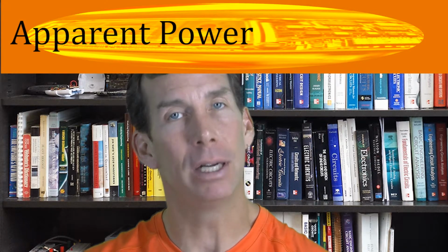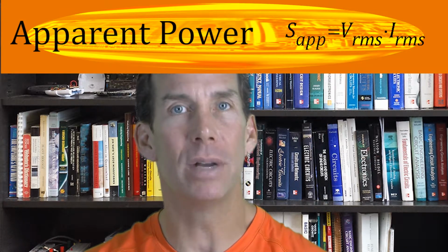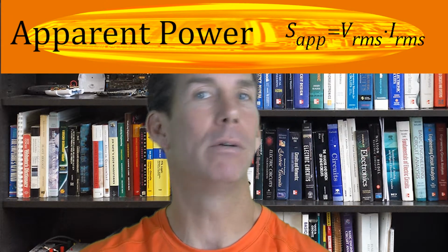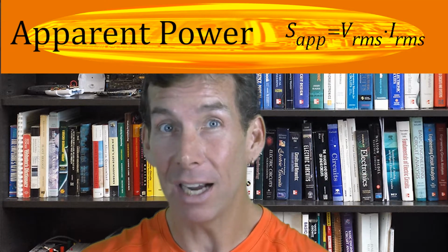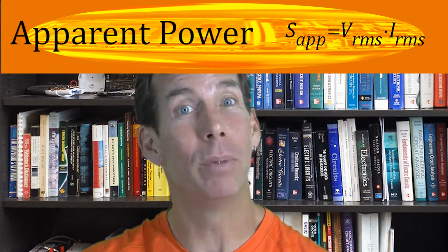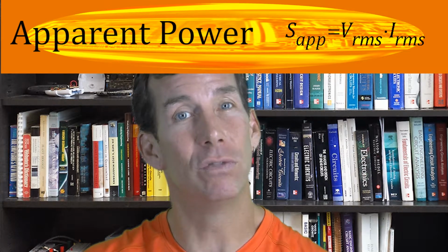Now we need to develop some vocabulary around this concept so we can begin to interpret what we have computed. Though the magnitude of the complex power is 5.76 voltamps, we see the average power is only 2.03 watts. That has to do with the phase angle difference between the load voltage and the load current. We have a rather straightforward way of handling this. The magnitude of the complex power is called the apparent power. Apparent power is the product of the RMS voltage and the RMS current. Apparent power does not indicate the amount of power being dissipated by something, as it may be entirely reactive, and therefore no power will be dissipated, but it does give an indicator of the magnitudes of the voltages and currents.